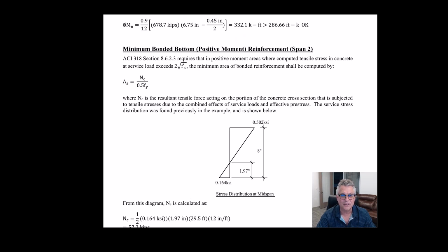Well, like I said, years of practice, people have decided that that's a realistic point to start worrying about cracking the concrete. In reality, you're going to have temperature and shrinkage happening before you ever pre-stress this thing while it's sitting in the forms, and you have restraint. You have restraint of the seismic system, the walls, even the non-seismic walls may be restraining your system. Stiff columns will restrain the system.